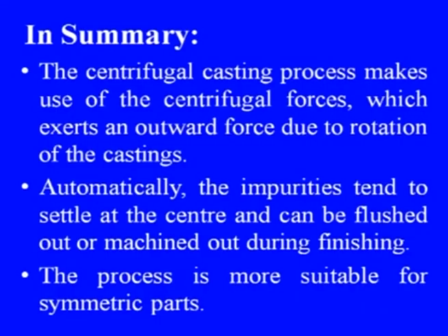Now, in summary, what we have learnt? The centrifugal casting process makes use of centrifugal forces, which exert an outward force due to rotation of the casting. Automatically, the impurities tend to settle at the center and can be flushed out or machined out during finishing. The process is more suitable for symmetric parts.